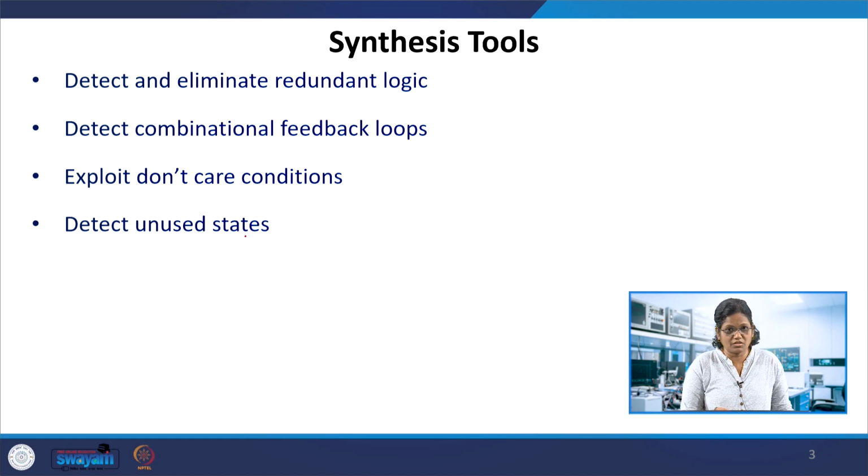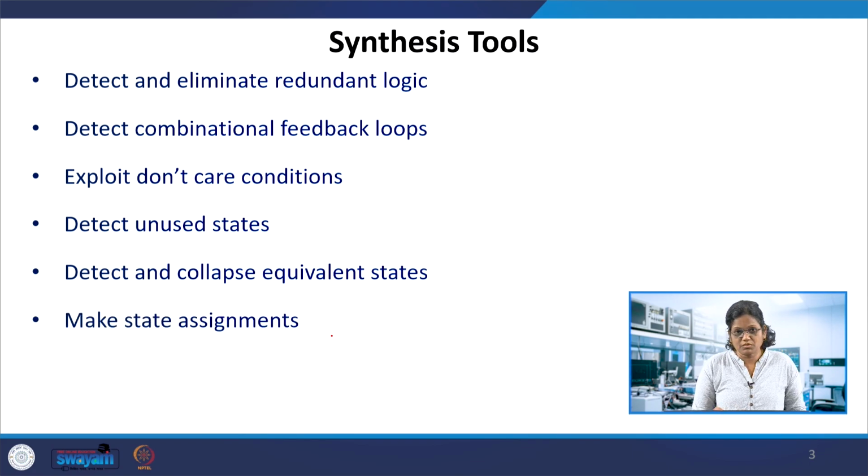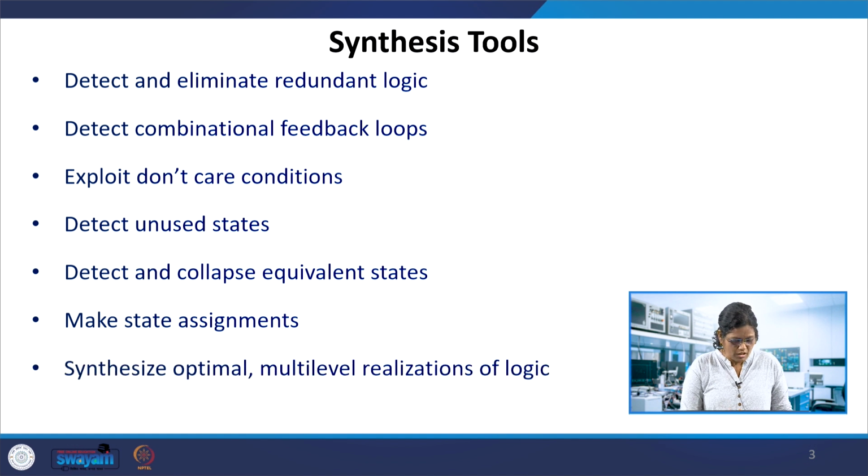If something is not used at all in the code, it detects them, and detects and collapses equivalent states. Some states may be equivalent, so it detects those. Also, it can mix some state assignments to reduce the number of states, so that the optimum states can be found.